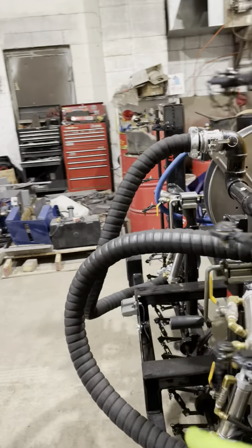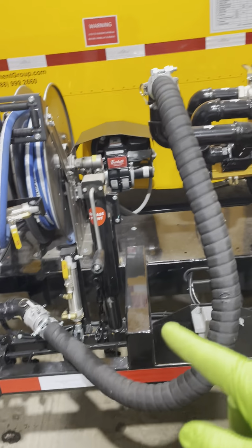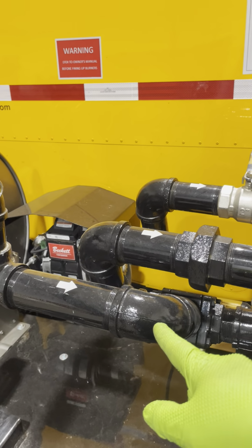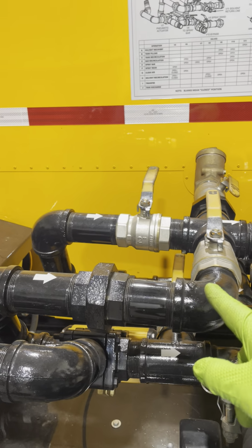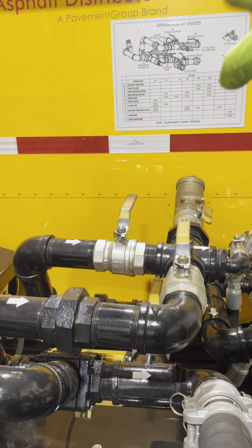It's going to come down along. We're pushing air, cleaning out the spray bar. It's coming up the other hose into the plumbing. It's bypassing valve 7 because valve 7 is closed. Taking a left, it's coming into the plumbing, back to the manifold, going across 8, which is open, and allowing it to go into 10, back to the tank.